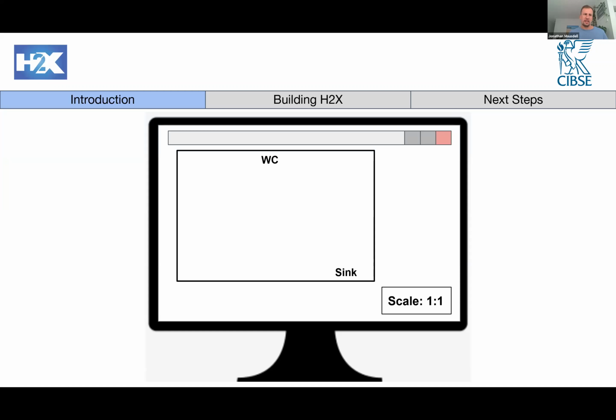So our concept at this stage was to just replicate the traditional process that we follow, but do it on the cloud. So this would work by, if we upload the architectural drawing into a software and make it so it's to scale, that would then mean that when a user draws pipes, the length is automatically measured. And then when we connect to the fixture, that fixture would have properties like loading units. So it would increase the flow rate as all these components are tied together. And we'll see it now as well from a concept level.